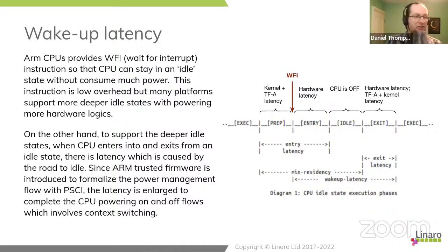Okay, so scratching and digging just a little bit deeper, wake-up latency isn't purely hardware. It's not purely the time it takes for the hardware to get kicked and for the CPU to come back to life, because during that path, it might well be executing firmware. It might have hit into the PSCI systems, which are implemented in trusted firmware in EL3. So it doesn't necessarily mean pure hardware latency.